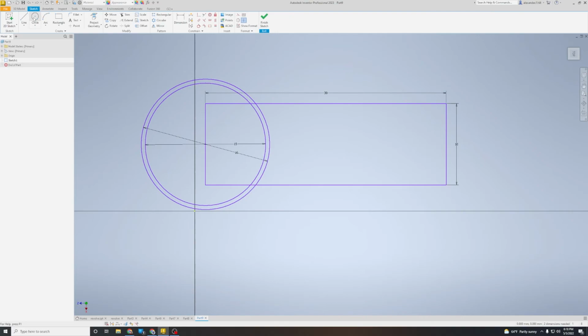I'm going to continue to use the circle tool. I'm going to make a few more rings. I want each ring that's solid, not the spacer rings, the solid rings to be 5 millimeters thick. But I want the spaces in between them to be 1 millimeter thick. I need to add 5 to 16. I get 21, and I can press enter. The next circle, starting at the same center point, will be one more than that, or 22.